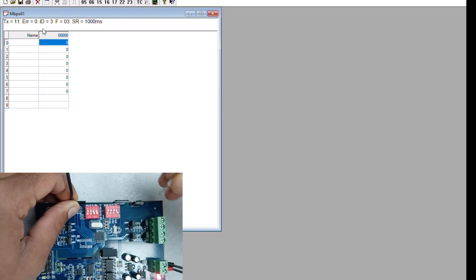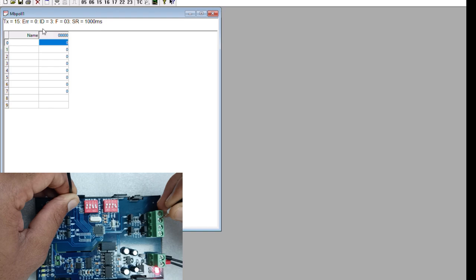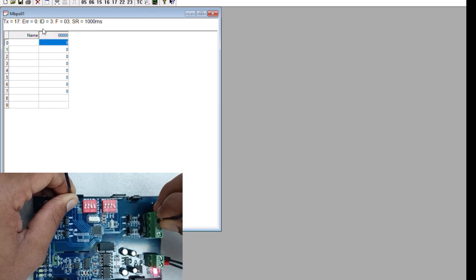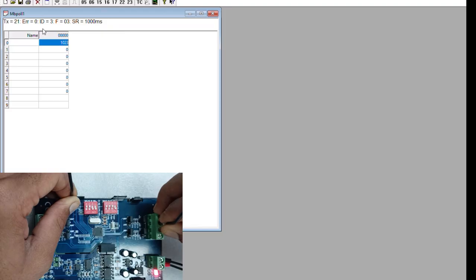Take the reference voltage of 5. This is the negative and this is the positive. Okay, I have to check with the positive AI1. Whenever I click here, short with here, I will get a 1023 resolution value.